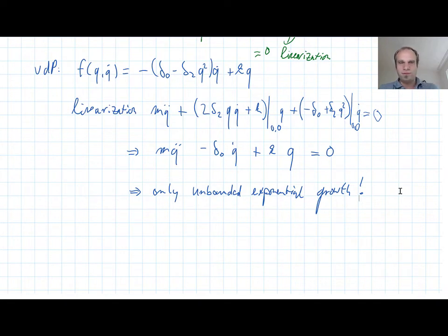Obviously, we have stiffness and damping that depends on amplitude now. That is actually a qualitative difference, you could say. But we could achieve the same effect with another parameter setting. If we change the preload, for instance, we could have a different effective stiffness, and with damping similarly.